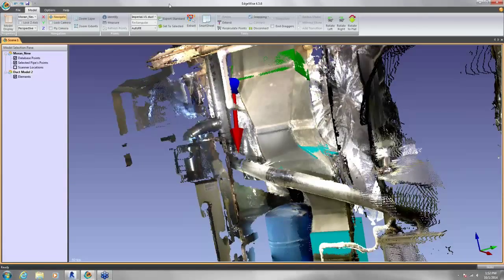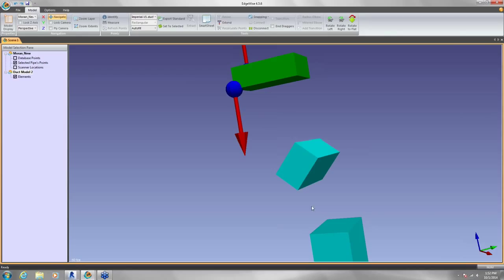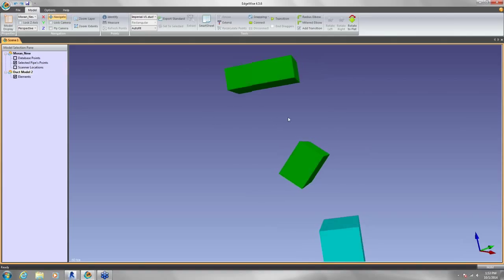All right, and you can see this didn't... I'd actually like this to line up vertically. So I want it to be parallel to the bottom guy. So let me turn off the point cloud, and I'm going to use my snapping tool to make it parallel to this bottom one. Then I'm going to grab both of these and do an alignment real quick, so when I do start making the elbows, they're going to line up with each other. So I'm going to use the align tool, and this just slightly rotates everything so that they fall in a nice clean line with the bottom one.